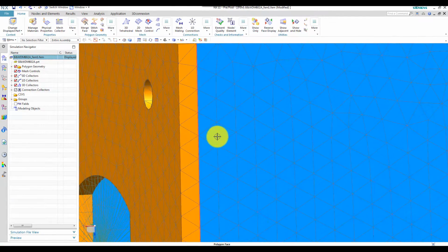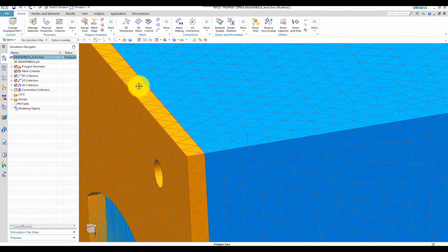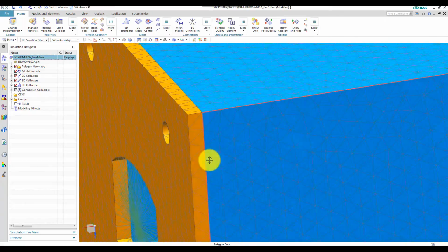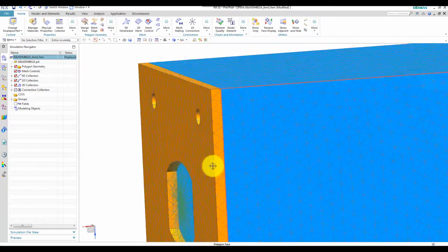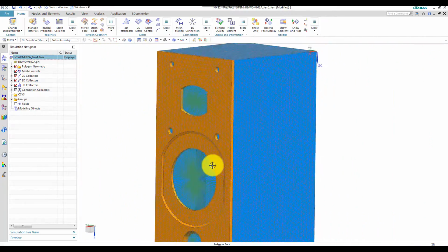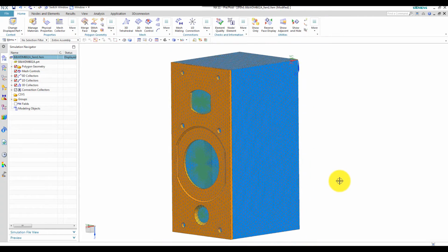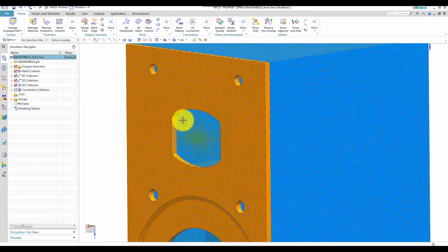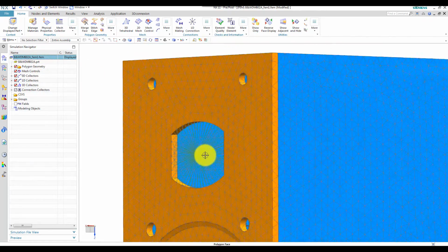And now you can see that the nodes are coincident. Well, there are no coincident nodes, but the meshes are aligned and connected. And that eliminates my unwanted rigid body modes. I only have 6 of them now. So then the FEM model is updated, unless I want to do something with the tweeter.